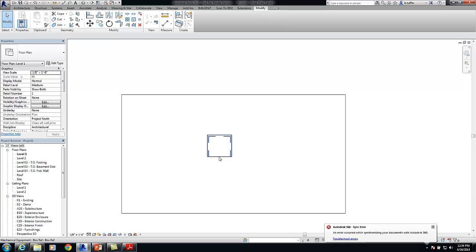Best practices, in my opinion, take the 3D model and work in your 3D model first. Start with the coarse level of detail. Lock it, fully constrain it, set everything up that you need. After you've done the coarse, move to the medium level of detail and or fine. I have a whiteboard in my office. A lot of the times I'll sketch out what I want it to look like, instead of just creating it on the fly. As you get to more complicated content, it can take a little bit of time.